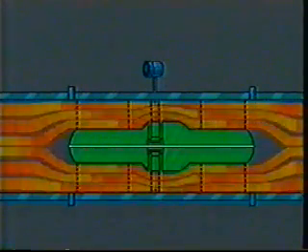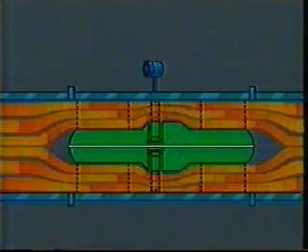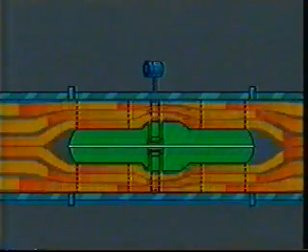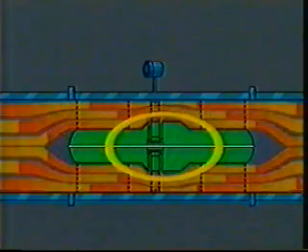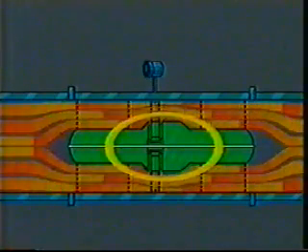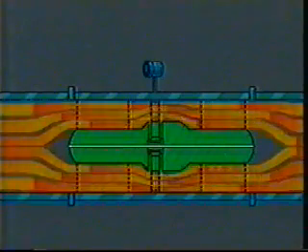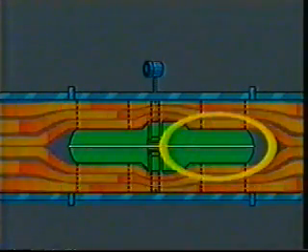Now, this floating occurs as liquid entering the meter is deflected outward by an upstream cone which increases its velocity and causes a slight pressure drop. After passing the turbine blades, the flow is redistributed. Because the rotor hub is larger than the upstream cone, some of the fluid flows directly over the hub. The rotor then floats in balance between the upstream cone and the downstream cone.